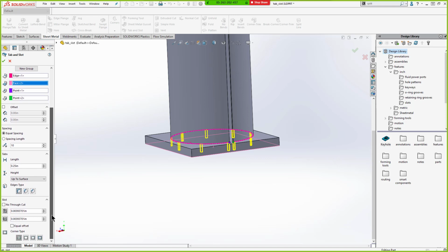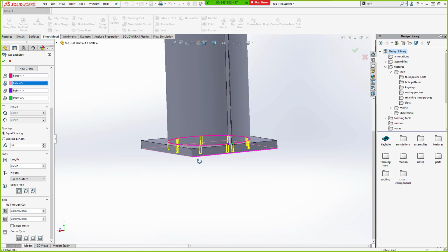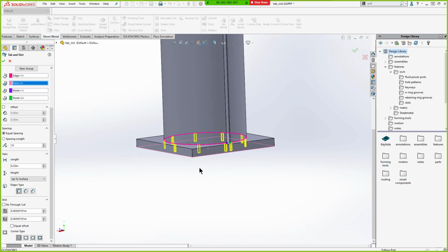And there's quite a few different options. You can choose the spacing, the quantity of tabs. There's quite a bit of adjustment. How much clearance is around there? Maybe you're going to plug weld these out on the bottom. That's kind of the idea that I was going for. And this is a self-locating fabrication process, so it goes past just self-locating parts.